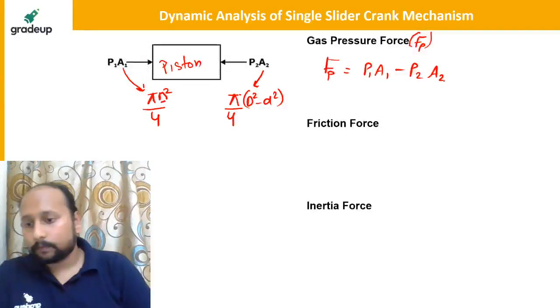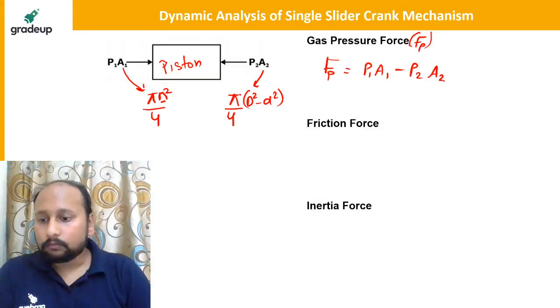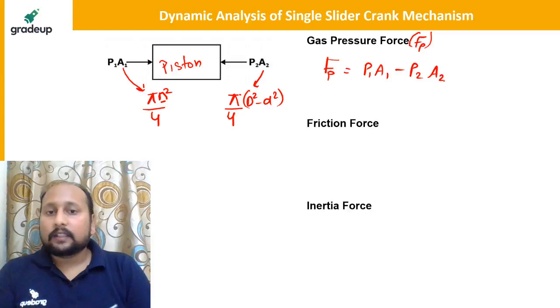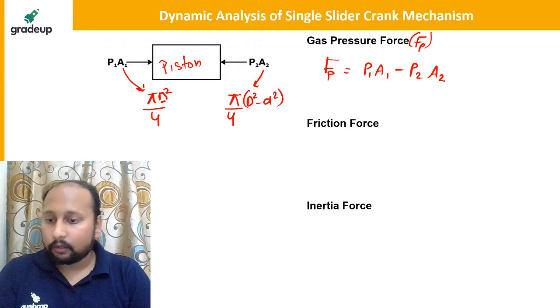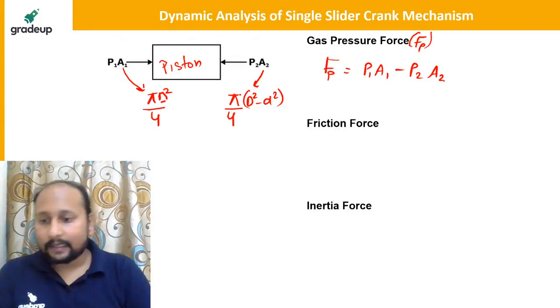Okay, so this will be a net pressure force, cross section area. Very good, Aditya. So this is your net pressure force denoted as Fp, P1 A1 minus P2 A2. Exactly, Vivek, correct. Now, if I talk about the frictional force, let me go to the previous diagram.